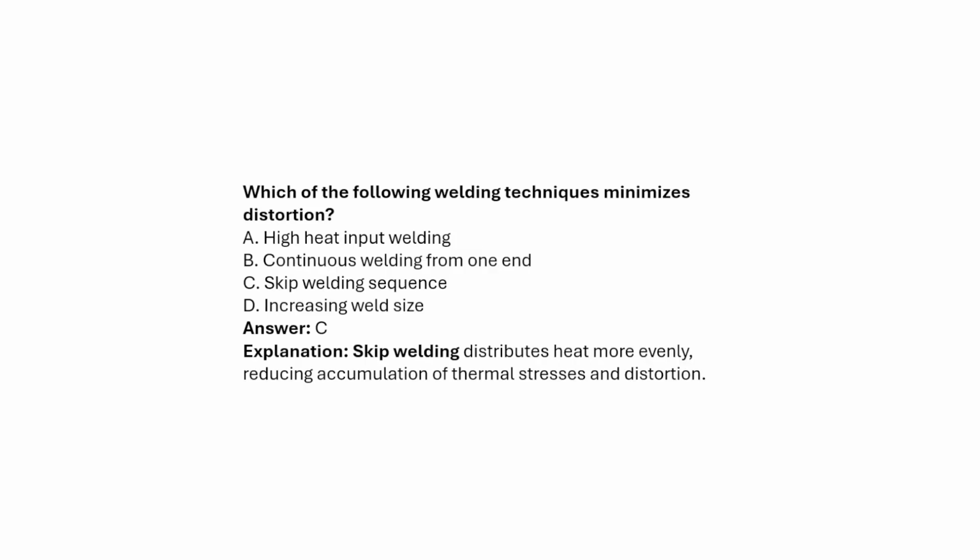Next, which of the following welding techniques minimizes distortion? High heat input welding, continuous welding from one end, skip welding sequence, or increasing the weld size.